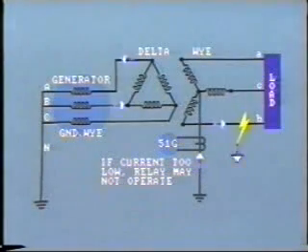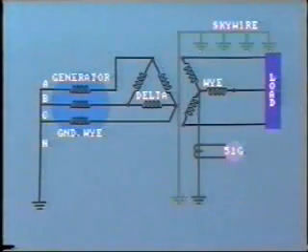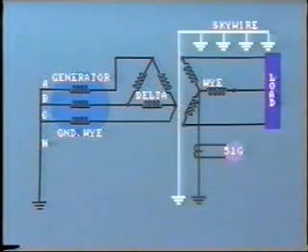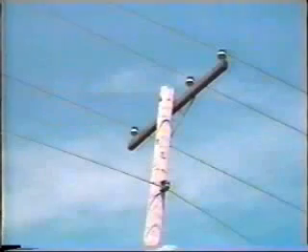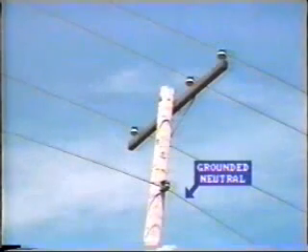But often another path is provided. For example, with high voltage transmission lines, the steel towers are connected together at the top by a bare ground wire or sky wire. This ground wire goes right back to the substation structure, which is, of course, grounded to the mat. Consequently, the ground wire provides a parallel path to current flow through the earth. Similarly, on four-wire distribution systems, the neutral fourth wire is usually grounded. And this, of course, provides an excellent path for ground fault current flow.